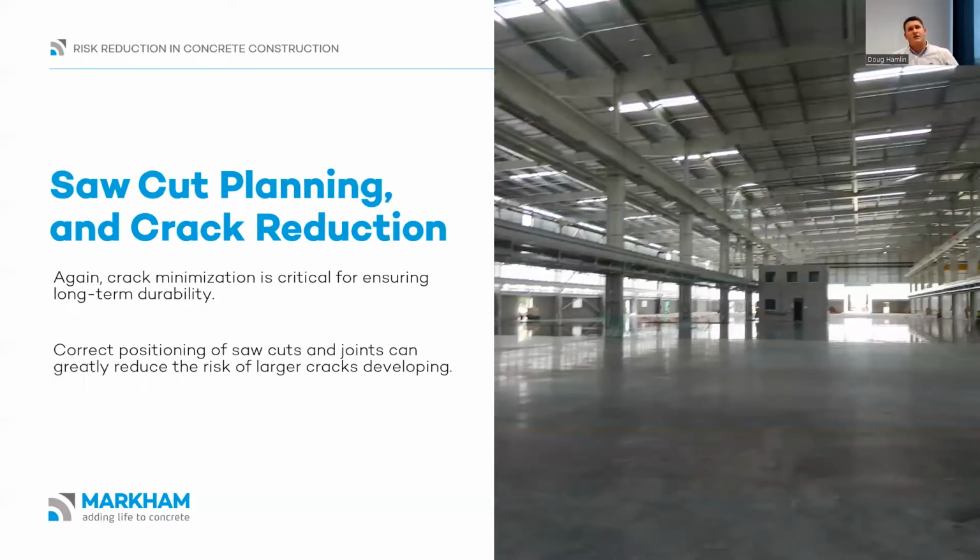The other area we see, I guess you could say it needs more input in construction planning, is the construction joint layout and doing all we can to mitigate random cracking on concrete slabs. So whether that's by a detailed saw cut plan on a slab pour before the pours even happen, or being smart around things like re-entry corners around columns, that type of thing.